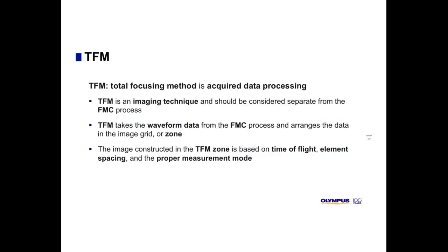TFM takes the waveform data from the FMC process and arranges the data in the image grid or zone that will be defined actually by the user. The image constructed in the TFM zone is based on time of flight, element spacing, and the proper measurement mode.